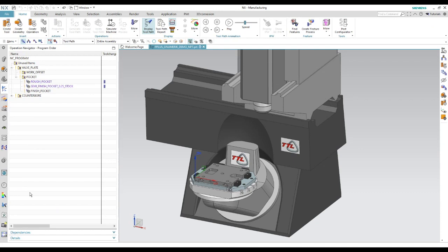Okay, so this demonstration will focus on the Probing Plus integration of Siemens numeric probing cycles into an NX CAM session. In machining applications, probing is typically used for three things: to set a work offset, to adjust a tool offset, or for general part measurement and inspection. We'll take a look at how all of these can be applied in NX with Probing Plus.